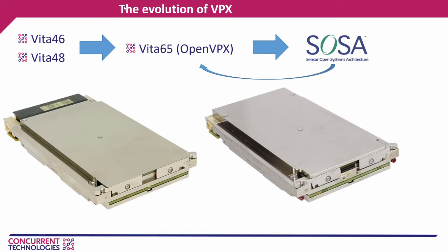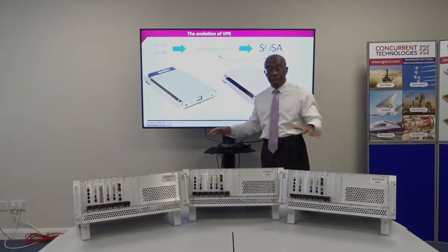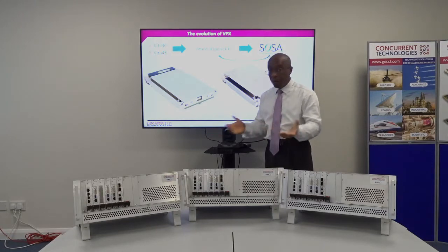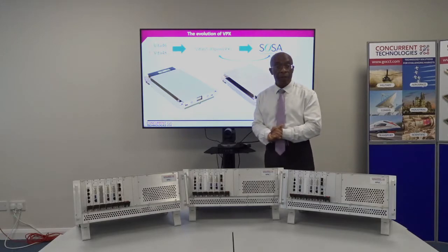The work that was done with OpenVPX carries on in the US with an initiative called SOSA, where the idea is to pretty much almost do the same as what was done in micro TCA, where all the signals on the pins have been predefined. So the idea is that it will then help interoperability. You will be able to use in a given slot boards from different manufacturers. That will help the ecosystem, hopefully potentially reduce the price of VPX products.